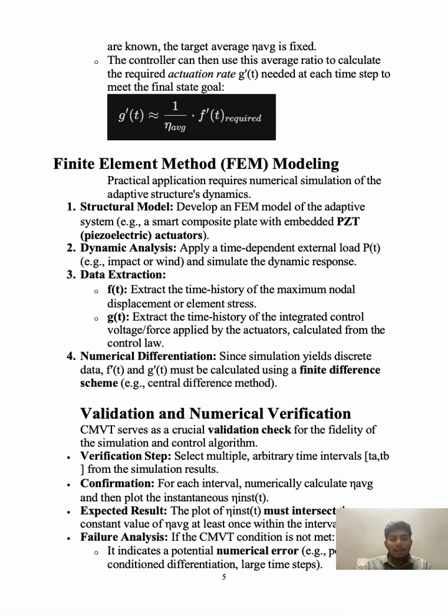Second one, the dynamic analysis. Apply a time-dependent external load P(t), for example impact or wind, and simulate the dynamic response. Third one, data extraction. f(t): extract the time history of a maximum nodal displacement or element strain. g(t): extract the time history of an integrated control voltage or force applied by the actuator, calculated from the control law.